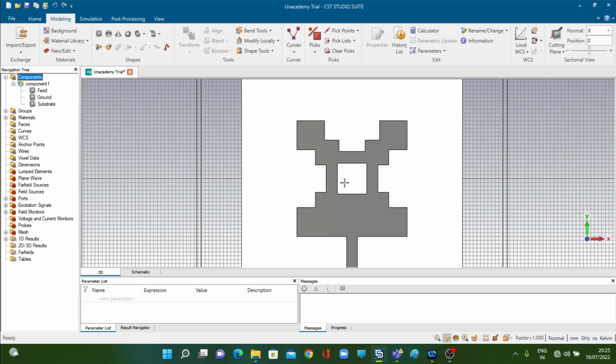and explained the importance of that in terms of the flow of surface current. As already mentioned, surface current does not flow through the center of the structure. It always finds its way along the peripheral regions. So the metallic portion at the center of the structure is actually having no effect on the result. So we can remove it. And as we are removing it, we can lower the amount of metallization, which helps us to reduce the conduction loss and also helps us in maintaining the cost effectiveness of actual prototyping of the prepared design.